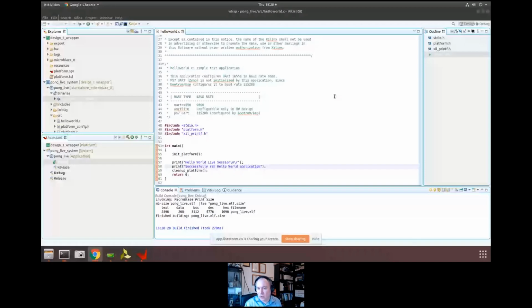You'll be able to see it work in the simulator, provided you give it a clock in the simulator. You'll be able to see it work, because I'm going to show you how to associate the bit files and how to generate the bit files and everything. Obviously, you won't actually be able to play the game, but you should be able to see it running in the Vivado simulator. You should be able to see that running through in there.